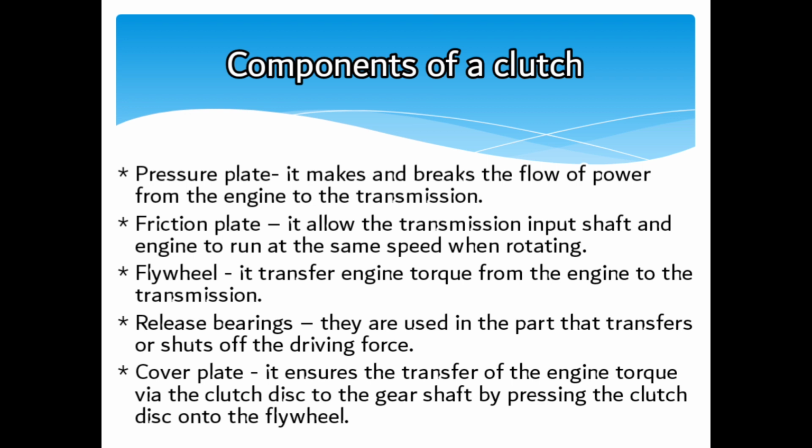When the driving force is shut off, the clutch release bearing is affected by a strong force from the high-speed rotating diaphragm spring, and this is why it starts to rotate suddenly.